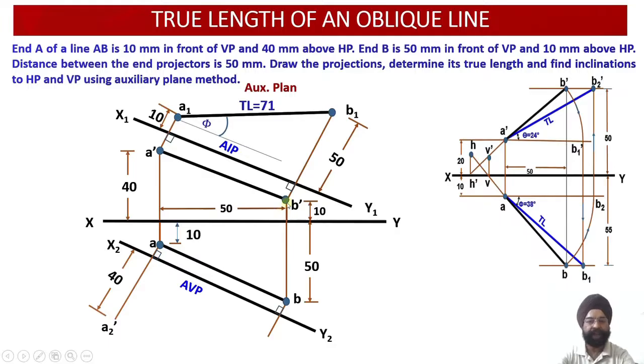Similarly, over here, what is the location of the coordinate B dash in the front view? This is 10 millimeter above. That is once again positive. So I'll measure this 10 millimeter from the plane x2 y2, positive, that is above my horizontal plane. So the name of this point is A2 dash, because the 2 comes from this being the second iteration. I am measuring the A dash distance, so obviously the name of this point is A2 dash.